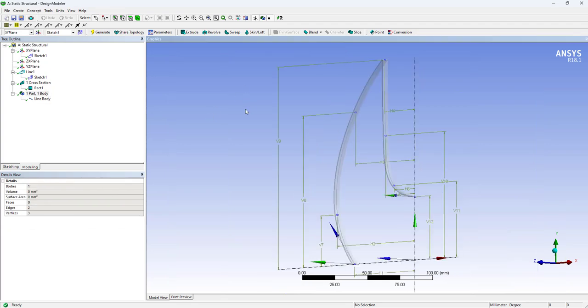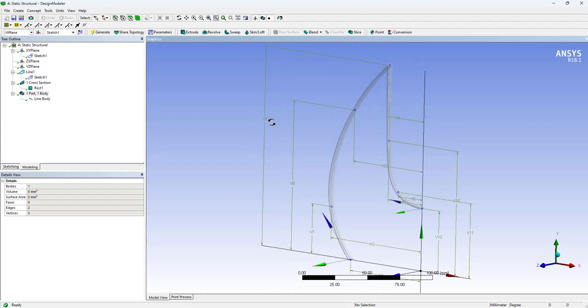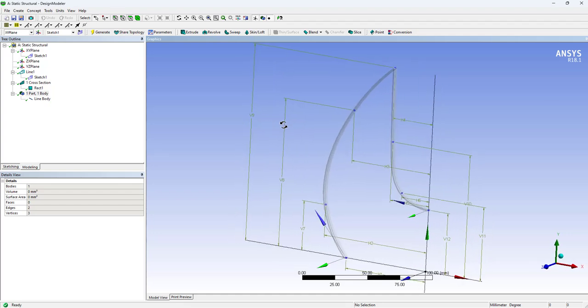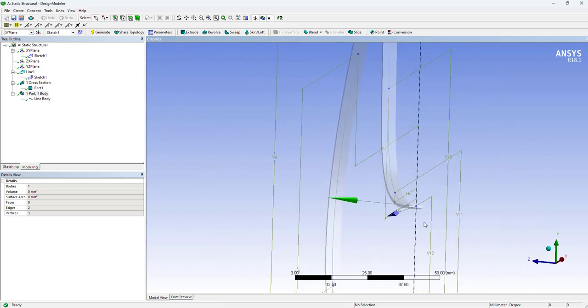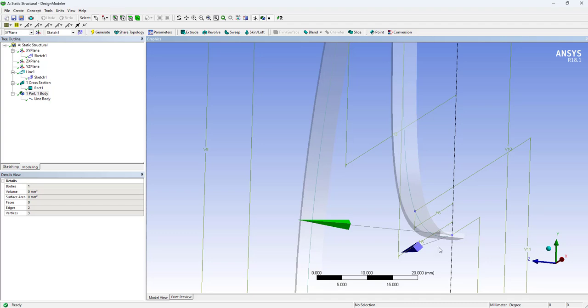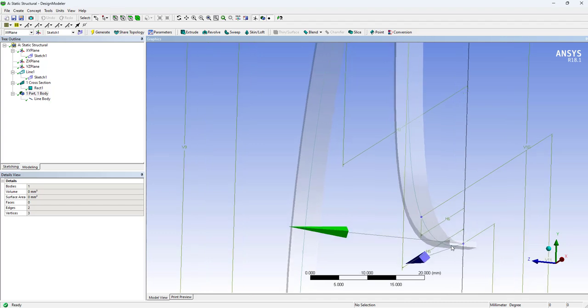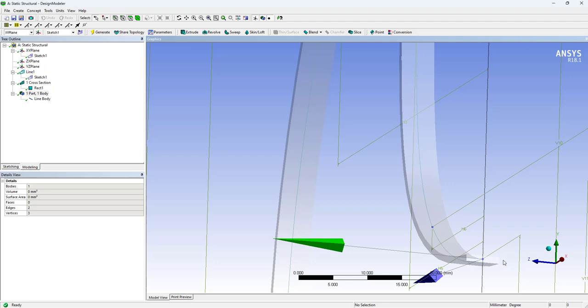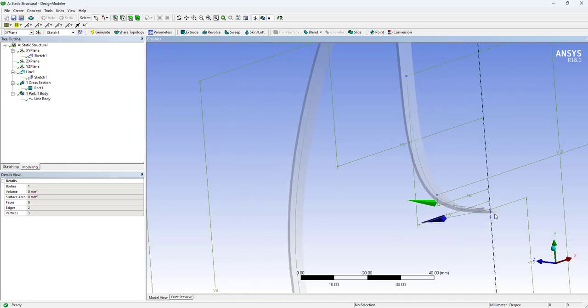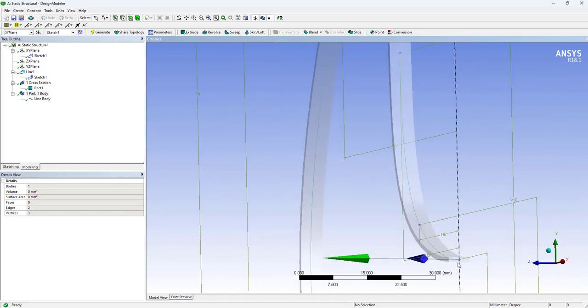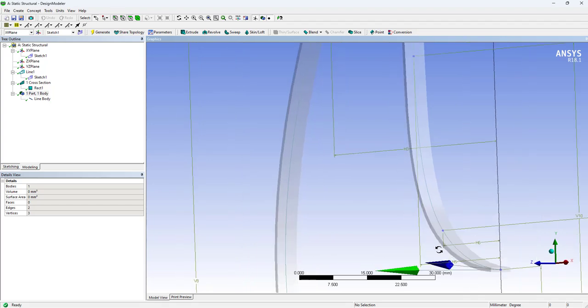There is one thing that we need to make sure of while modeling line elements, that the cross section of the line element must be oriented correctly. Here by default this is correctly assigned, in that we have this small length of the rectangle in the y direction, and you can see the height or base, which is the larger length, in the z direction.